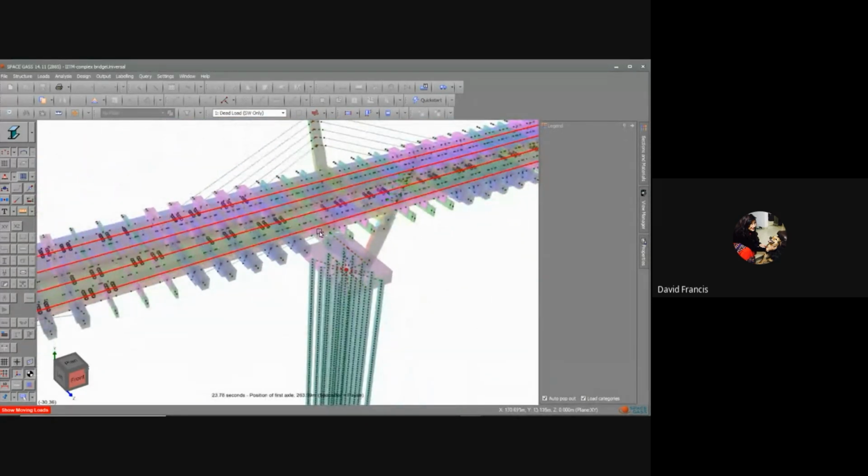So at each step, you define a step, so at every one second or whatever it is, you're snapshotting and getting a primary load case, which are then combined into other primary loads that you select. So dead load, for example, and live load if you want them included. All right, so I'll escape that.